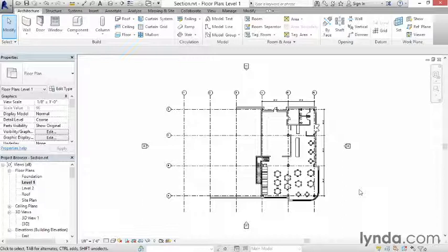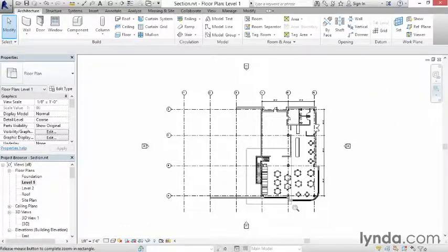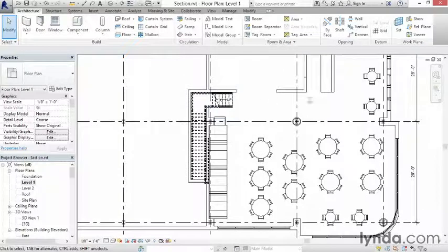I'm in a project called Section, and we're just going to cut a couple sections in here and take a look at how the tool works. So let's think about an area where we want to get a better look at how things are coming together. And I'm thinking that this stair area here with the balcony up above is a good choice. I'll start off by zooming in on that location. And I'm going to create a couple different sections that cut through this stairwell area and show us what's going on there. So I'm going to do the first one right here.